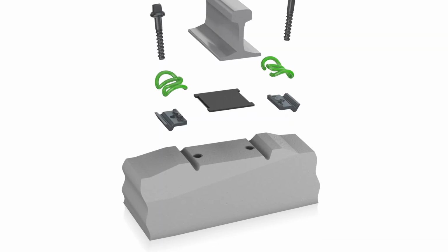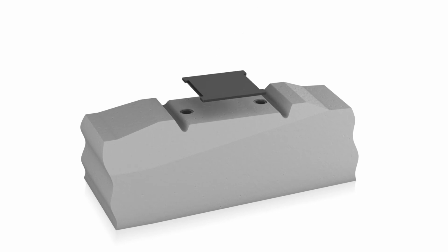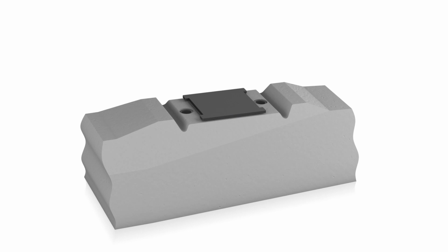Let's have a look at a typical fastening for concrete sleepers. There are large numbers of fastenings for concrete sleepers, which are also constantly being improved and further developed. The link between the rail and the sleeper is a construction in itself, which can take on very different forms depending on the design of the sleeper and the type of the rail. The rail inclination is achieved by a recess in the sleeper with the angle to be achieved, usually 1:40. A sleeper pad is installed between the rail base and the sleeper to increase friction and give some elasticity between the rail and the sleeper. The elastic material reduces vibrations and wear on the ballast.